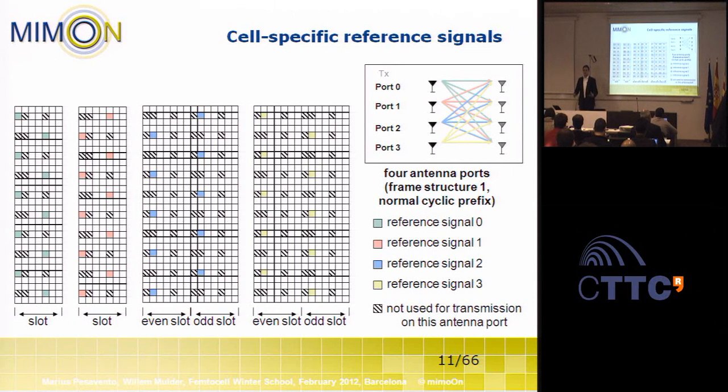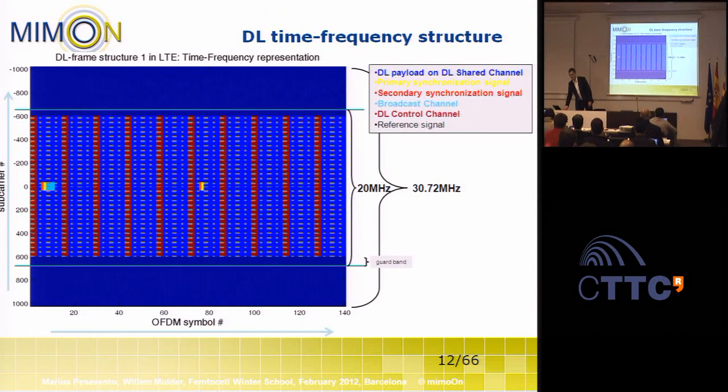So there's a trade-off, and we see that, and the idea is, if higher order MIMO is used in the system, then we should have some reasonably static environment. Channels should not be changing that quickly. We are not traveling at 350 kilometers per hour in this case.